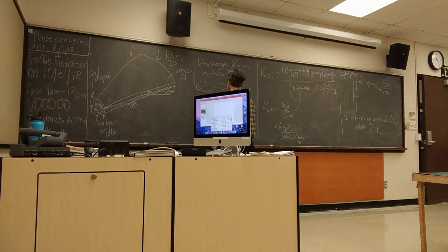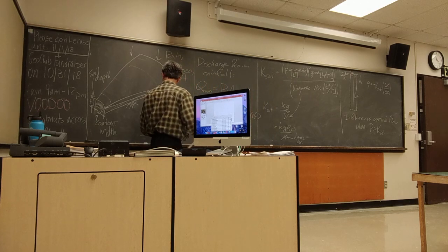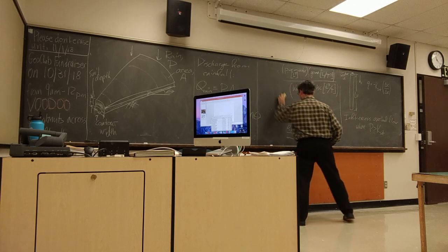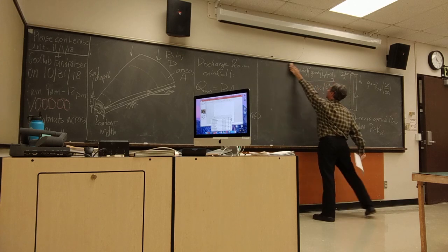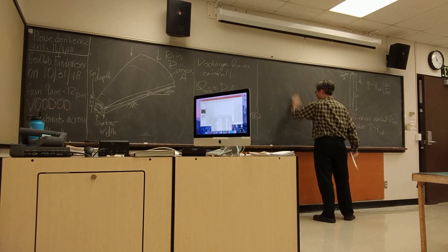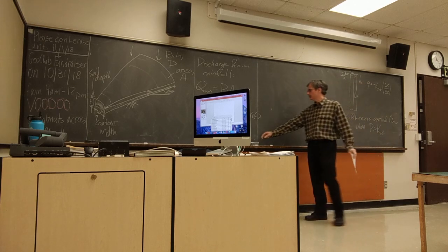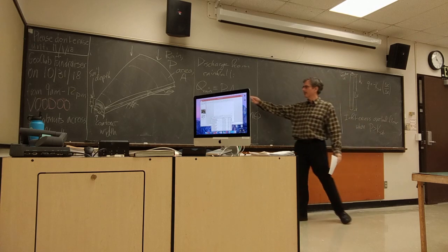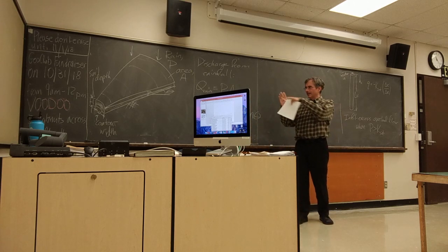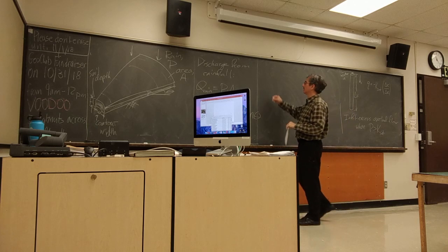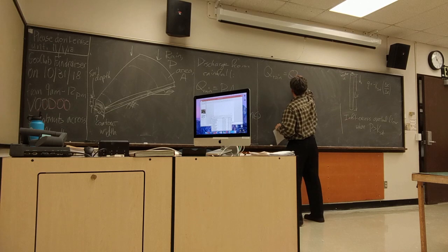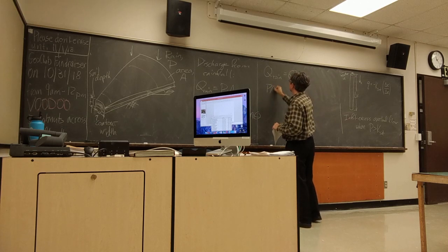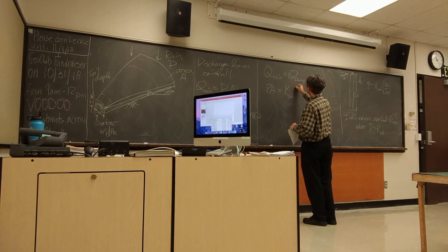So Ksat times the soil thickness times the contour width times sine theta. Whatever I want to know, this gives me an equation to solve for it. I can say these two things are equal, at least in the ideal case that I've outlined here. And so if I set the one equal to the other, I've got a nice simple equation.